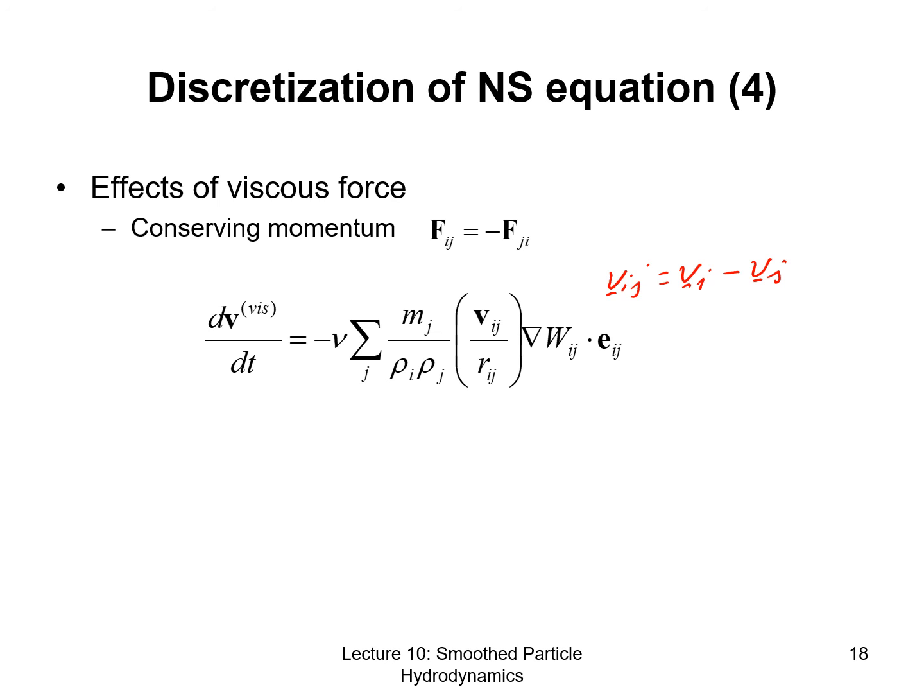So the SPH method has very similar properties to molecular dynamics. It has mass conservation, because every particle's mass does not change as we use a Lagrangian formulation, and momentum is conserved because all the formulations are in the form of a force and a reverse force. So basically, that's the SPH method. It has very good conservation properties, same as molecular dynamics.